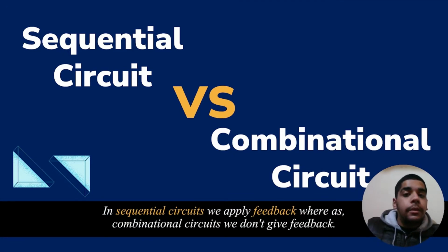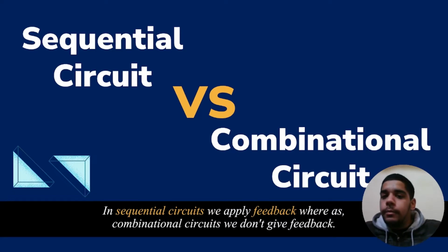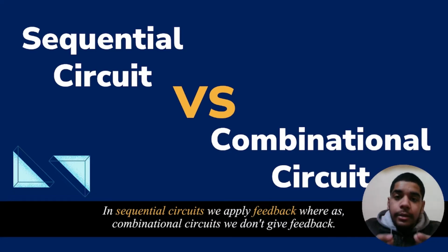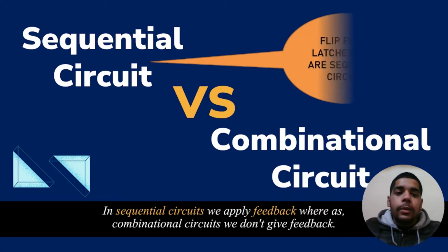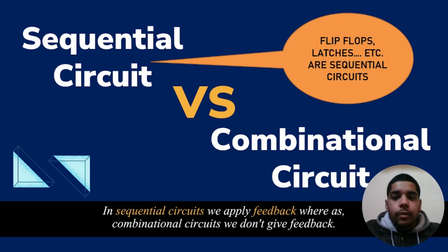What is the difference between a sequential and a combinational circuit? Both of these are circuits, but the major difference, which helps us understand flip-flops in a better way, is this: in a sequential circuit we apply feedback, but in a combinational circuit we don't apply feedback. Just focus on one thing, feedback. What we are studying in this seminar is what we call sequential circuits. Flip-flops and latches are sequential circuits.